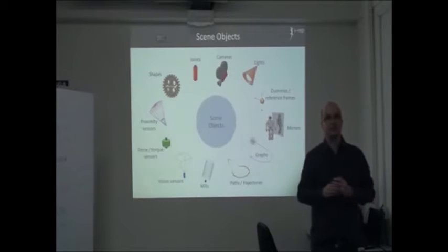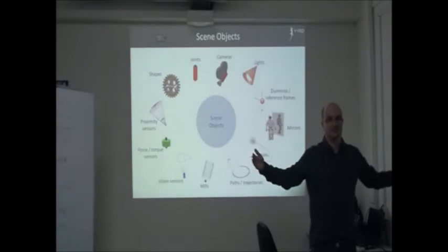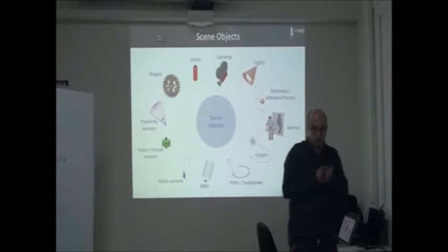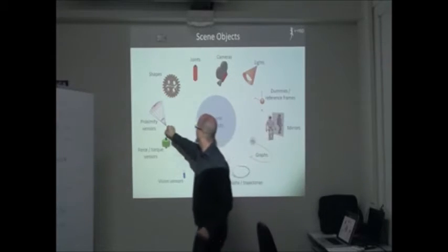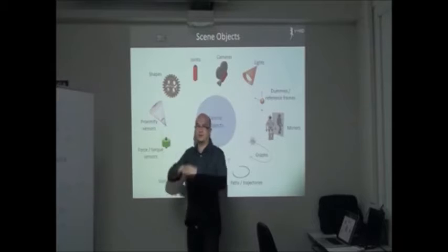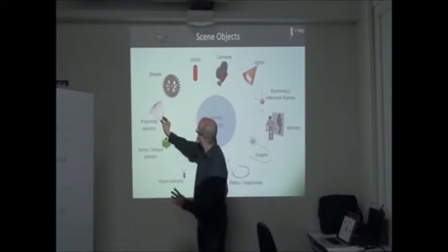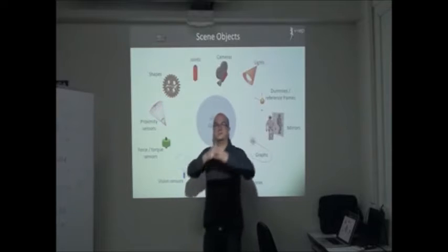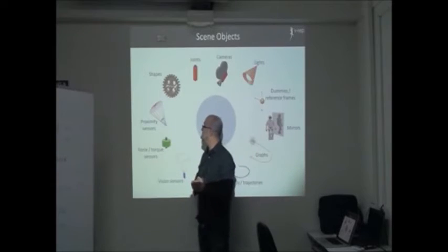Divided by the speed of sound, you have the distance. That's the sonar. It works like this: you have a kind of cone of information. After a while you're not detecting anymore, so you can define the angle of the cone, the size of the cone also, and put some noise on it if you want.